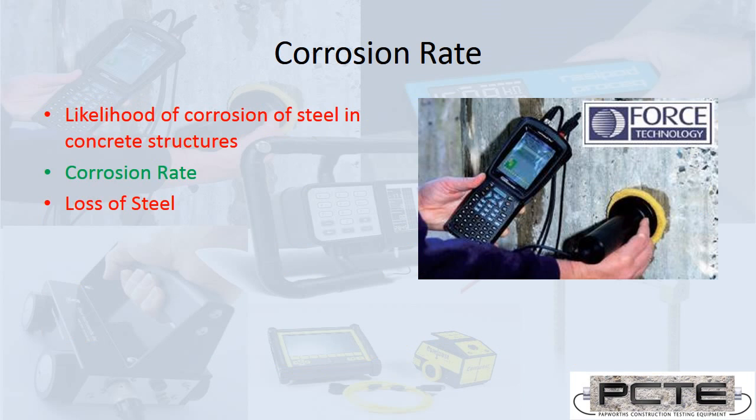So this tool is used to establish the rate of corrosion. It's also a more useful tool in some of those difficult cases where you've got wetter concrete or situations where half-cell potential is less useful a tool to scope out regions of corrosion.